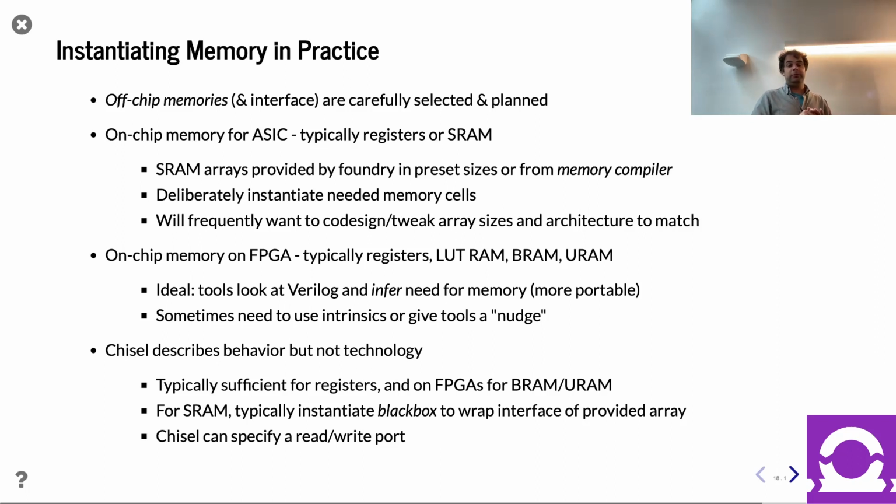And so, yeah, when you are working with these ASIC SRAMs, you have to literally say, I want this particular instance, this particular SRAM macro to be instantiated, right? Sometimes you want to try which one you're using to see how it changes power, performance, area, that kind of stuff. But it's a pretty deliberate, intentional thing that's done consciously.